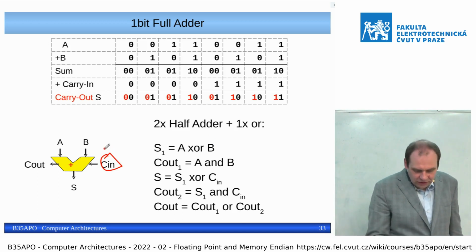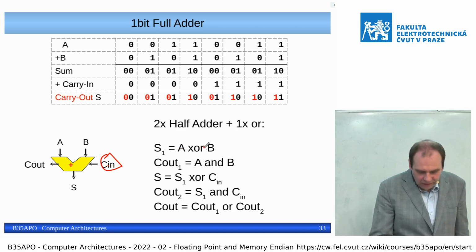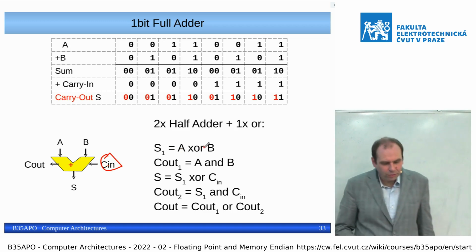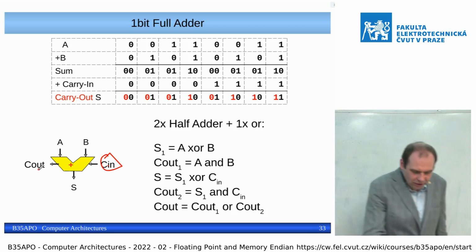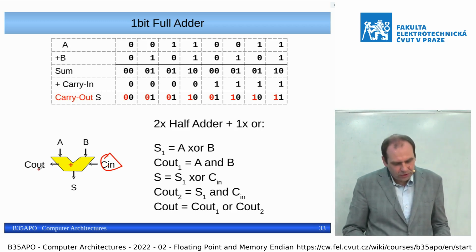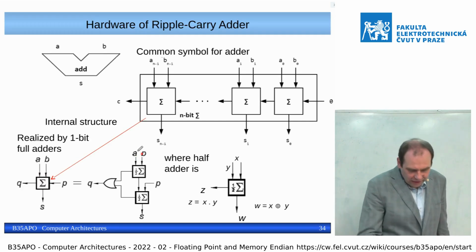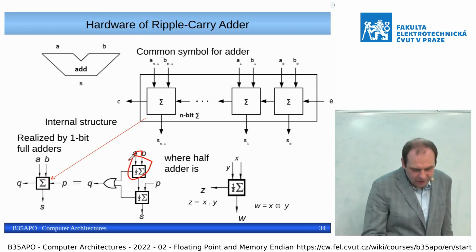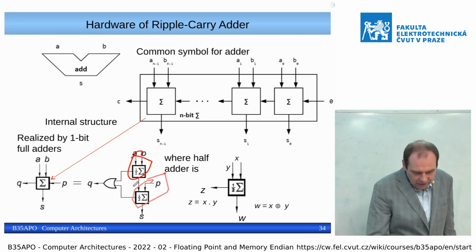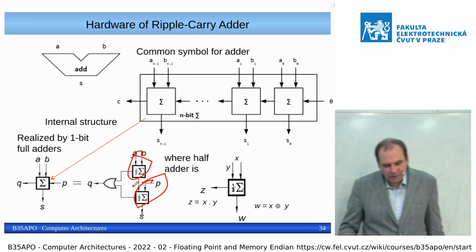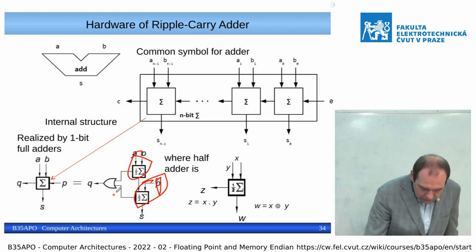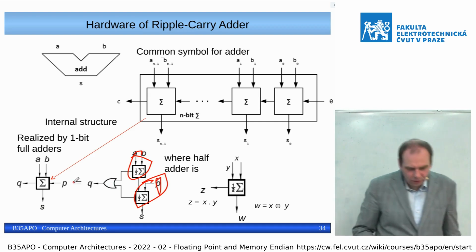Basically, the addition is relatively simple in the bit, so it is the exclusive OR of the incoming carry and both inputs. It is a little more complex with the output carry, which can be generated in the first half, where we add A and B, or in the second half, where we add the propagated carry to the logic.